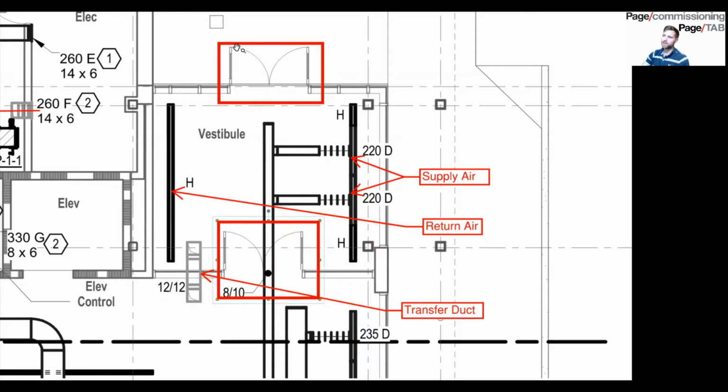As soon as he did that, I felt a big rush of air come in. That tells you that if the air is going inside the building, the building is negative, so you have more exhaust than you do outside air. This space below opens to the entire building, with pretty large stairwells that go to the rest of the floors, so measuring it here gives you an idea of what the rest of the building is doing.